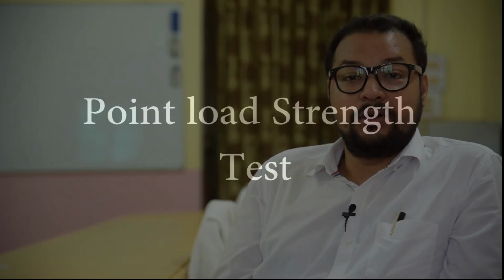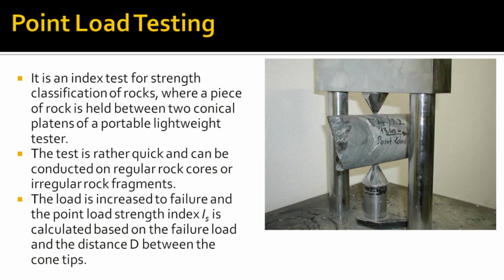However, there is a test called the point load strength test, which can be conducted on pieces, lumps of broken rocks, which gives us a fair idea about the uniaxial compressive strength of the same rock. There have been ample researches on the correlation between uniaxial compressive strength and point load strength of the rock material.